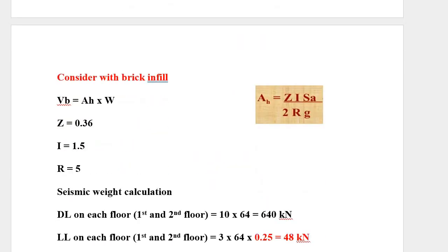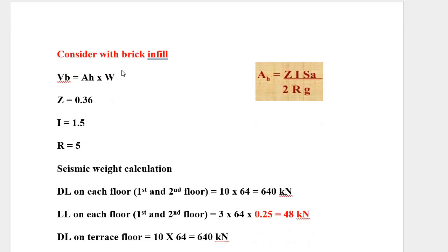Here they have not mentioned any condition, so I'm assuming it is a brick infill. Consider with a brick infill. This is a condition I'm assuming. So according to this assumption, a few values will change. So we should calculate VB, that is base shear.